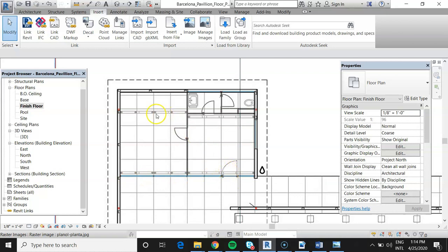And then in here, I'm not clear, this looks like it was drawn as glass. I'm not sure why it appears there's glass there. That's a little confusing. These are obviously, this is a bathroom, so it would not be glass unless it were frosted. I would draw these as very slender, maybe even like 2-inch generic walls, and then I would put doors in them, and that's just so that when we print the floor plan, we have something in here.